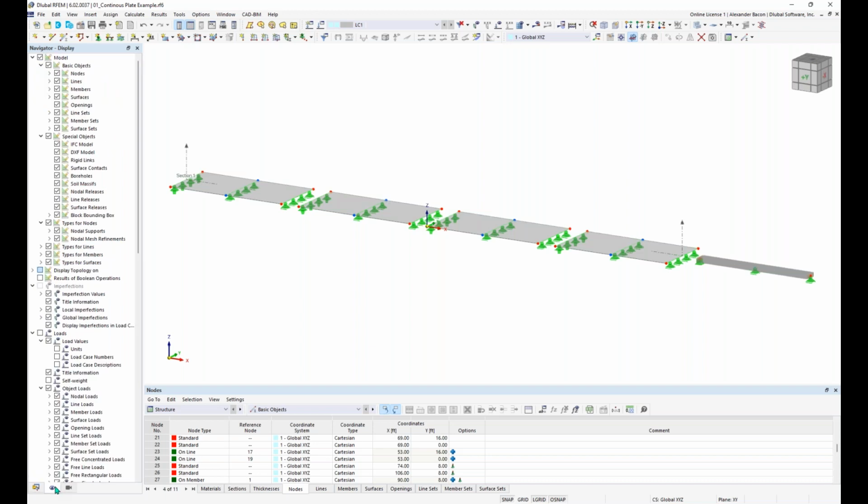Next, we have the display tab down here at the bottom. So under the display tab, you can turn on or off the graphical rendering of objects and other settings. Turning the render of something off and on just turns off the rendering, and it will still be considered within the calculation even though you can't see it in the work window.